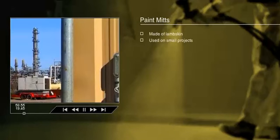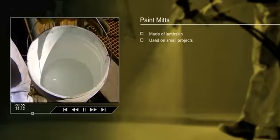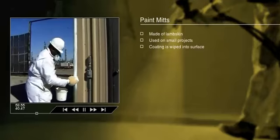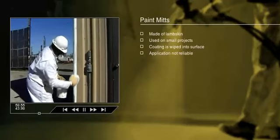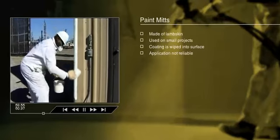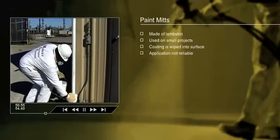Mitts are generally made of lambskin and are lined with solvent-resistant material. They have limited use in the application of coatings for industrial use. Generally, they are used on small projects, such as for coating handrails, small diameter piping in racks, etc., where roller or spray application are not feasible. In practice, the mitt is dipped into the coating and is used to wipe the coating onto the surface. The coating film achieved is not of reliable quality, so the use of this type of equipment should be restricted to areas where appearance is more important than long-term protection.